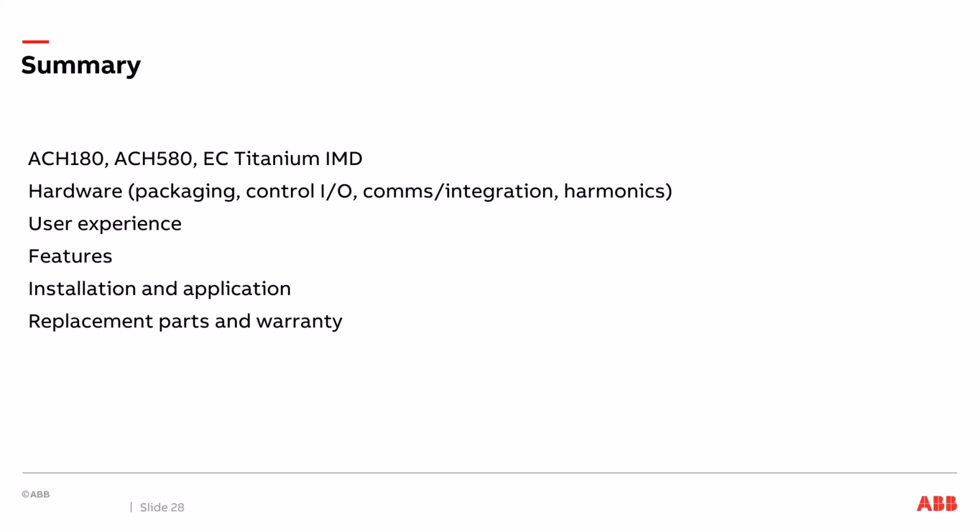There's pros and cons to both. And really, if it's going to be on the motor, definitely consider the environment that that motor is going to be in, because sometimes it's better for electronics to be in a different environment from where the motor is, as far as, say, for example, is an air handler in a heating mode running at 105 degrees or something along those lines.